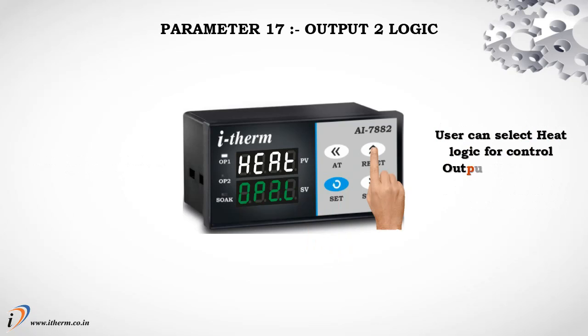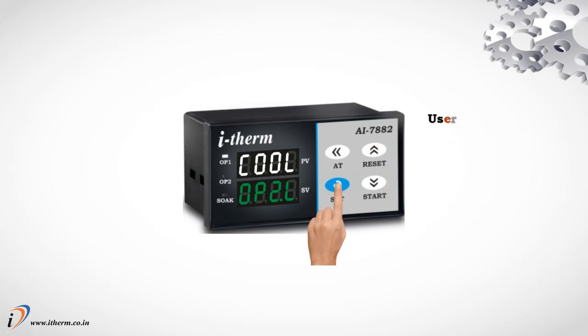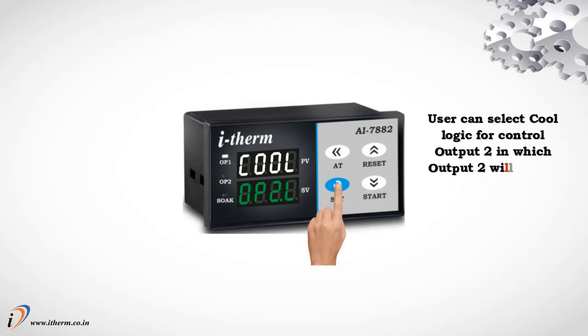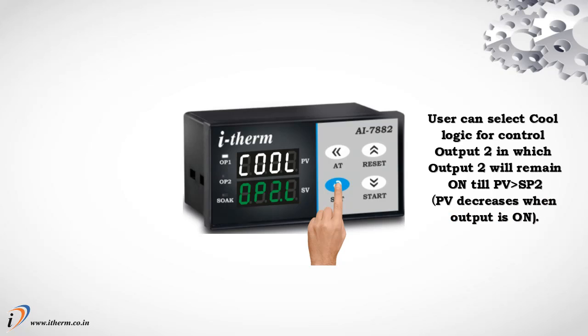Parameter 17, Output 2 logic. The user can select heat logic for control output 2, in which output 2 will remain on until the process value is less than setpoint 2. The user can select cool logic for control output 2, in which output 2 will remain on until the process value is greater than setpoint 2.